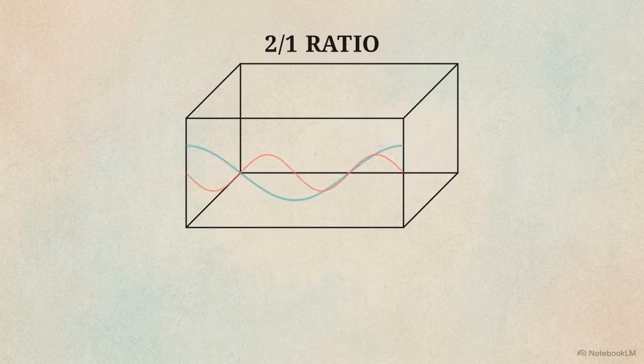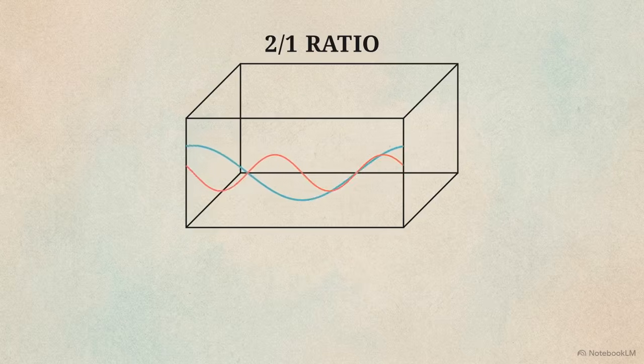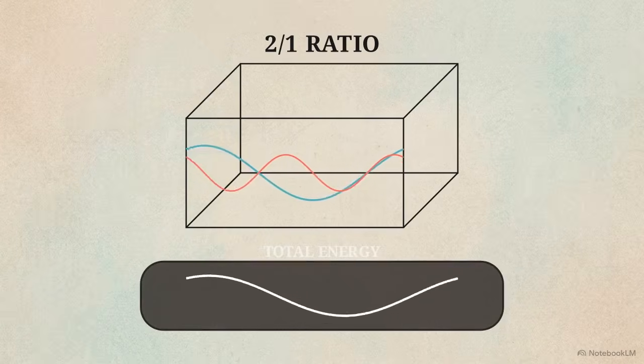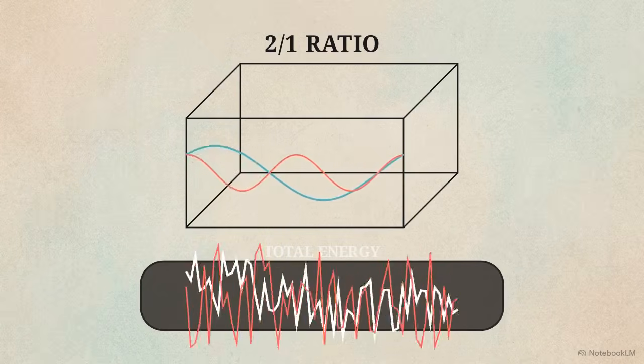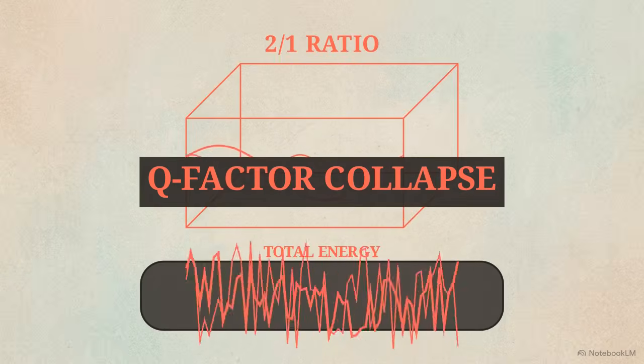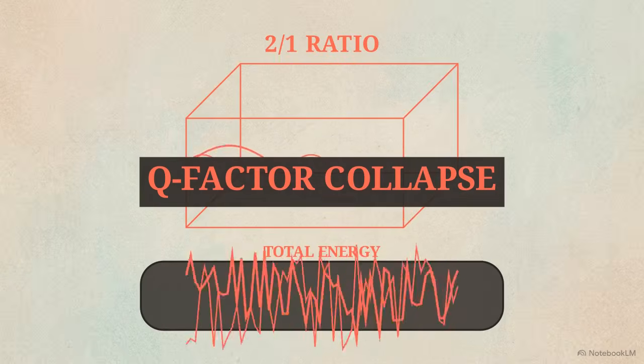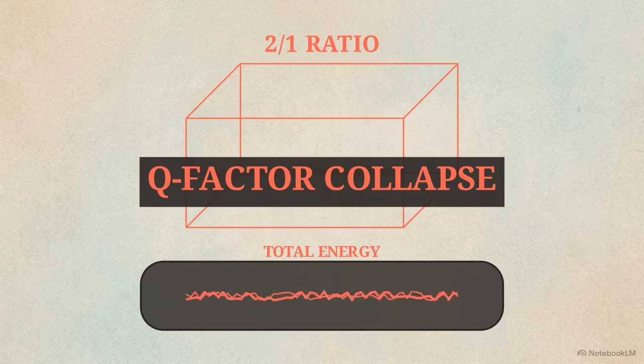If you try to build this system in a standard box, it fails immediately. The problem is modal degeneracy. When multiple resonance patterns share the same frequency inside a cavity, acoustic energy bleeds between them. Any shape built with simple dimension ratios, like 2:1 or 3:2, will cause these harmonics to overlap. The energy scatters into parasitic vibrations, destroying the Q factor and stopping the pump.